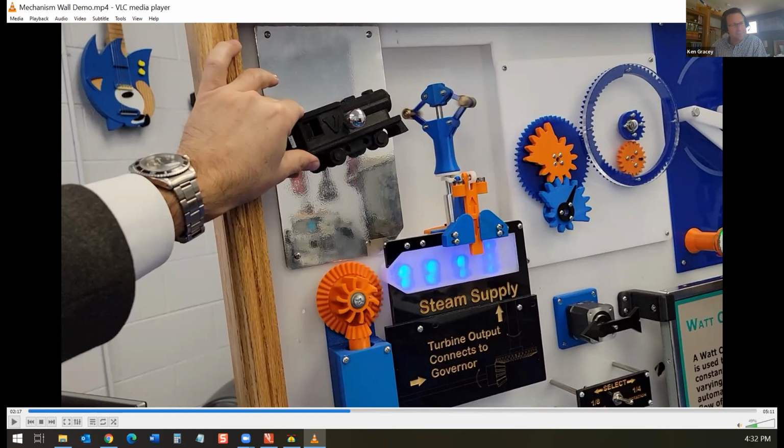And CNC routing is a bit more complicated. For that, it's the advanced mechatronics course where they're building the guitars, and I kind of help them through that. For those of you that haven't used CNC routers, it's not the same as 3D printing. 3D printing is two-dimensional printing, one layer at a time, that adds up to 3 dimensions. CNC machining, you're literally dealing with 3 dimensions all the time. If you're not careful with your tool path, you'll hit clamps or you'll cut off a piece you actually wanted to keep.